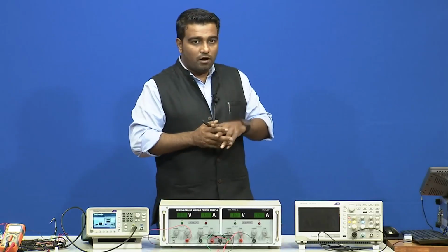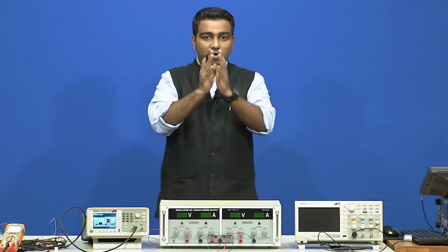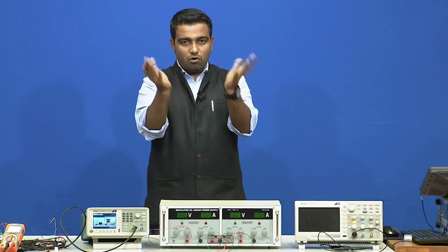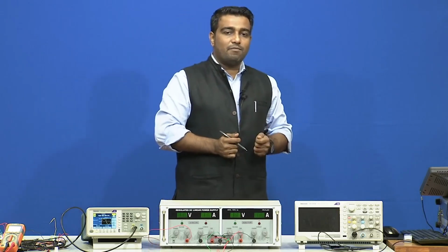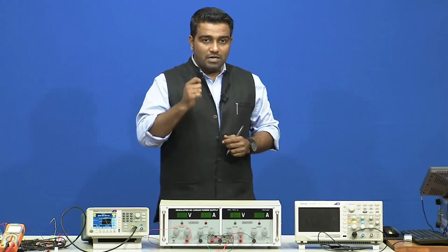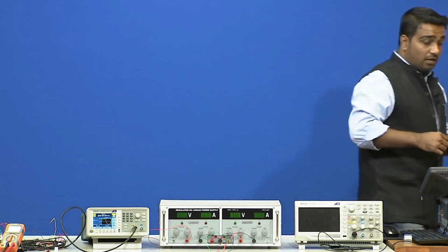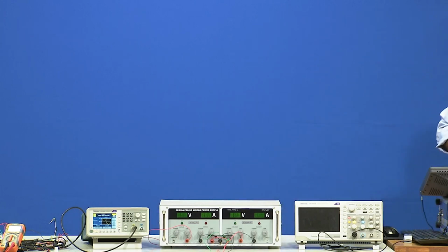That means if I give you a sensor which is 1 kilo ohm, and you see a change of 500 ohms, then it is a really sensitive sensor and you have a broad range to operate. In that case, your life becomes easier in creating the electronic module, but if the change is small, then it is very difficult. So, we are talking about the commonly used sensors or resistive sensors.